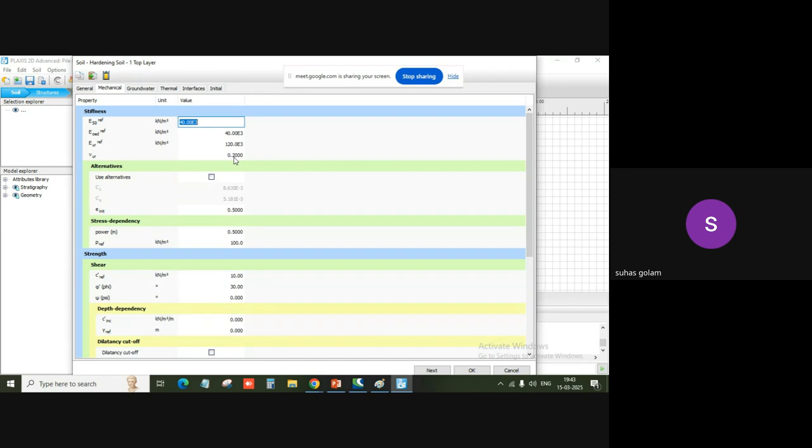0.2 is close to that of a rock, kind of. It should be like 0.2, 0.22 or 0.3 you can consider. Actually, if you increase the stiffness, it will be on the lower side. You are correct. For rocks, the stiffness values are quite higher, sometimes 80,000 or something. So in that case, you can go a bit lower, also 0.18 to 0.15. So these values are just for reference. If you are modeling, you need to be very careful again.